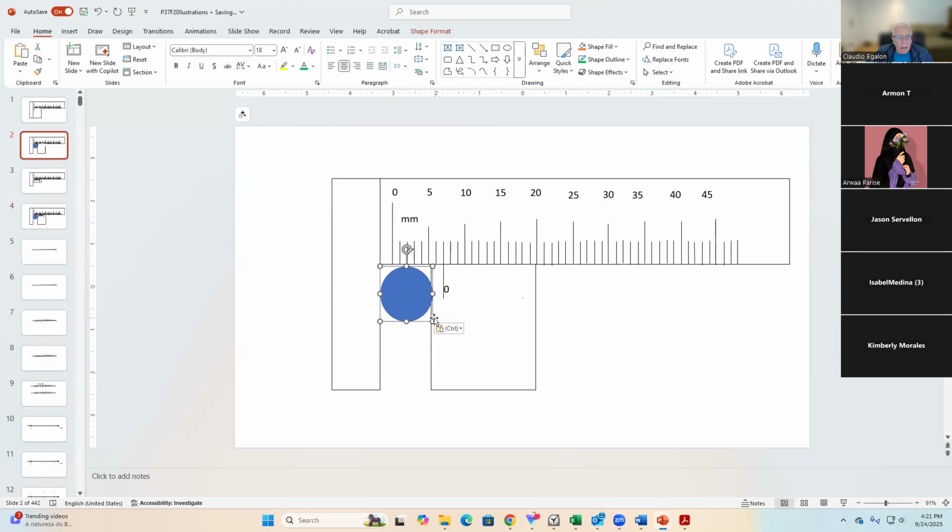It is slightly larger than, okay, now we got it. So you look at the zero here in the vernier scale to find out the diameter of this object. For now, I'm just uncovering the vernier scale. So this vernier caliper is working just like a regular ruler. So at this point here, you can say that's around 7 millimeters, okay? 7 millimeters.